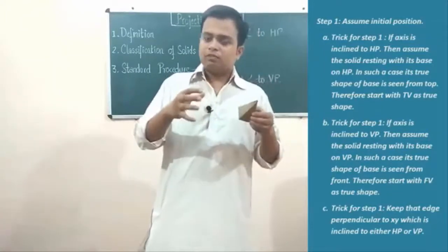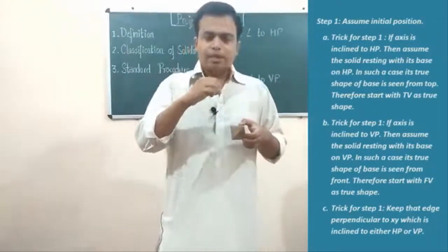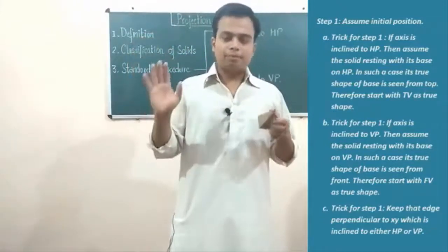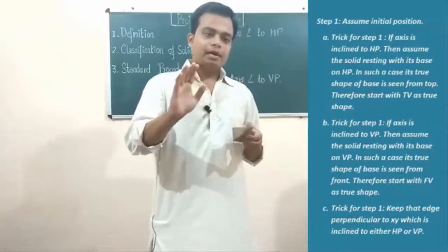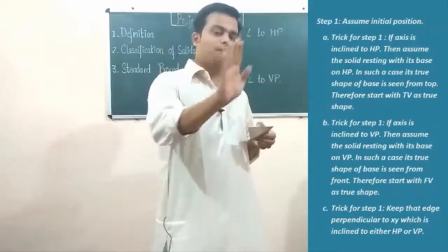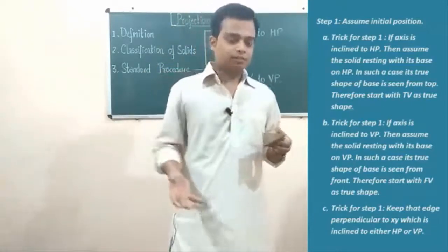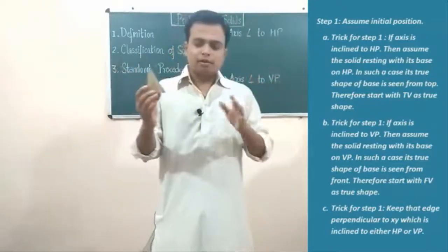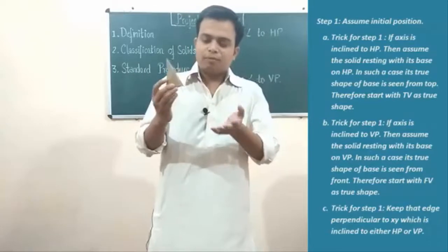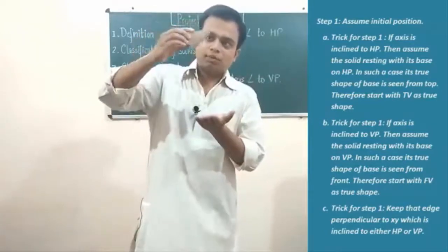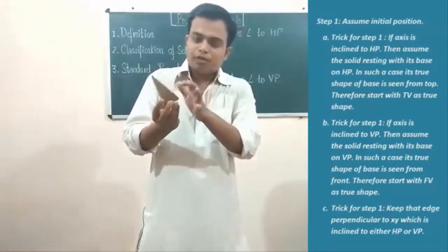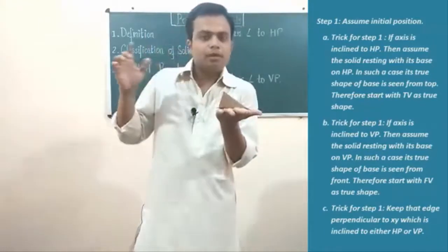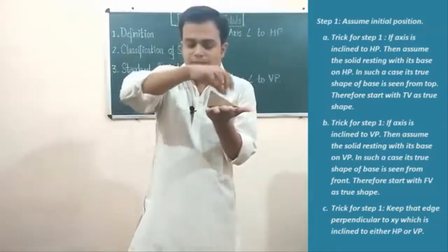And if you are successful in creating the correct step 1, then I'm pretty much sure that you're going to go ahead and create step 2 and step 3 in perfect fashion. Alright. Now, there may be a question in which you're going to be asked that one of the triangular faces of the pyramid is resting on the horizontal plane like this. One of the triangular faces in the pyramid is resting on the HP. In such a case, your initial assumption will be like this.